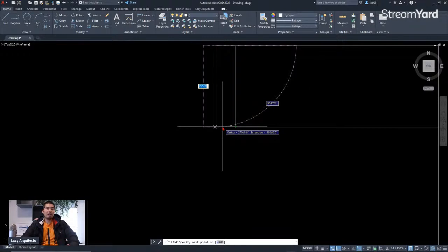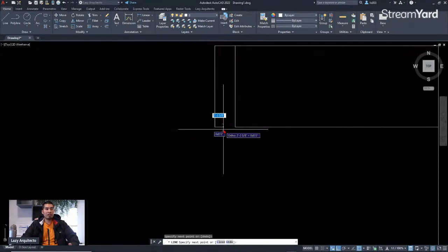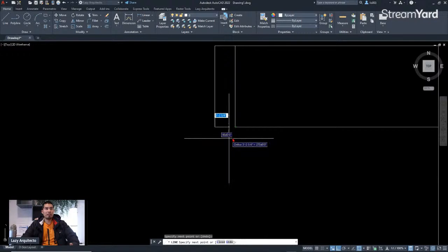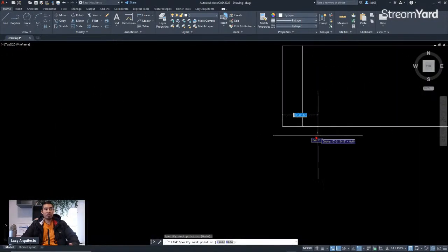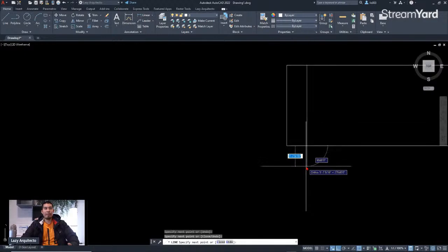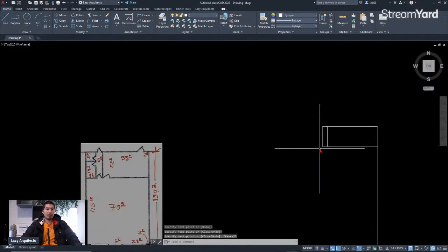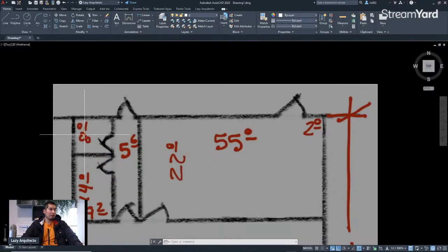So at this point, I can simply left click once, and you will have your corridor at the same 22 feet. So again, if I go back here, I can simply close my corridor by clicking on this line or endpoint like so. So I can press escape, and then I'll have my corridor ready. Let's keep moving with the same idea on this 8 feet room over here.